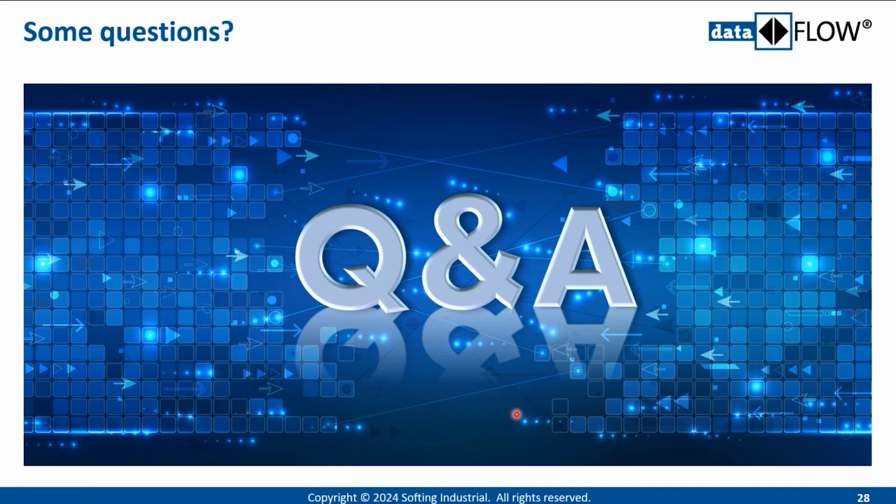Question from Dimitro Suravel. What do I need for the development and testing of field devices? Yeah, okay, that would be more a question to a field device manufacturer. I mean, from a switch perspective, not that much. If it's purely APL, it's only a layer 2 switch. You could even use an unmanaged switch to do that. All you have to do is have access to your APL field devices, then you do the testing. So the switch itself wouldn't add a lot.